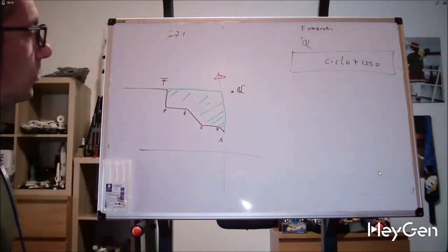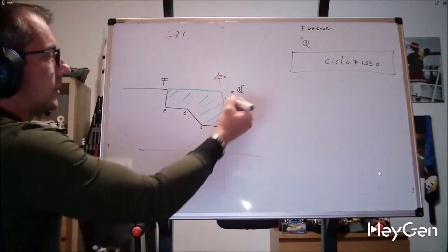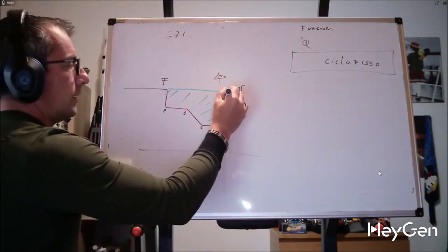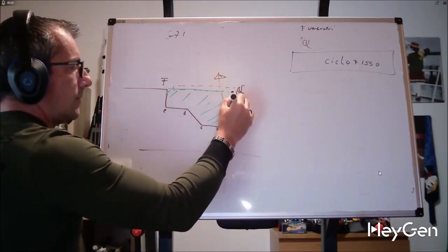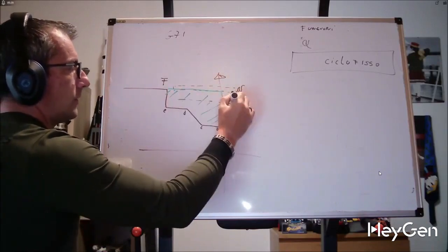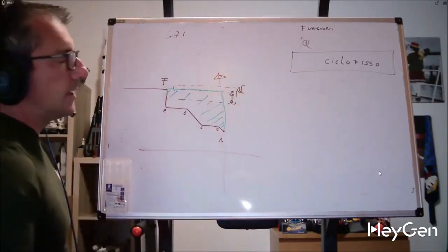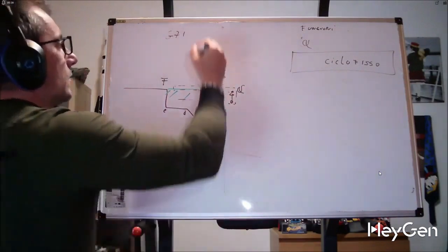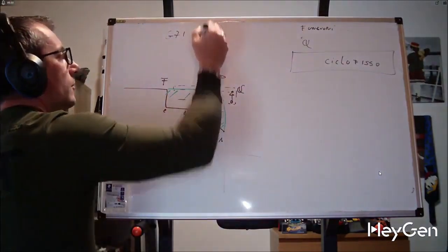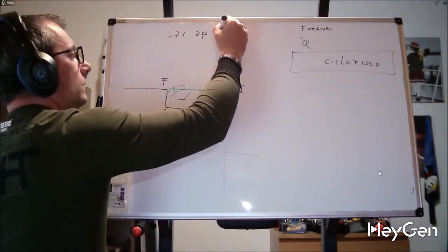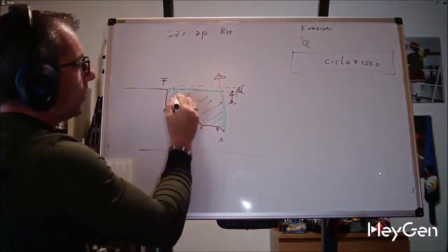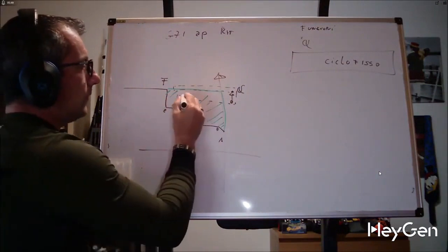Then we should give the depth of cut, meaning every time I make a longitudinal pass, I lift up, I come away, and I don't lower, and I start again. This distance is the radial depth of cut. So let's call it out, depth of cut, and R for return, meaning how much I retract.